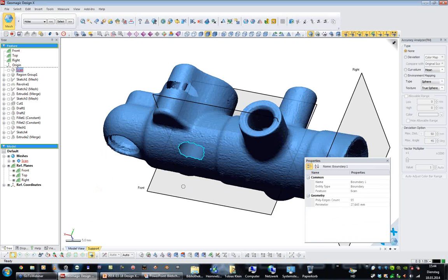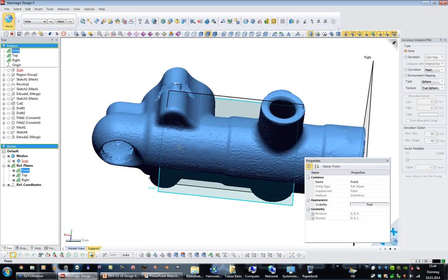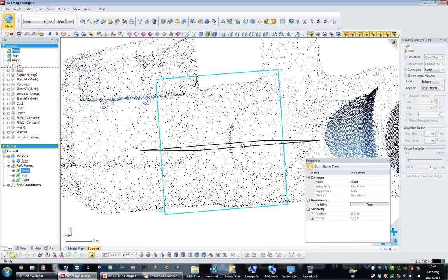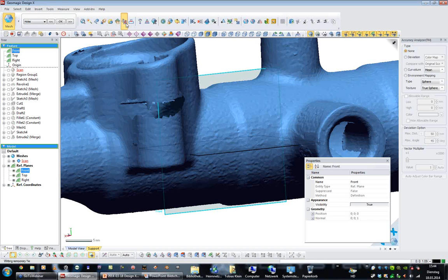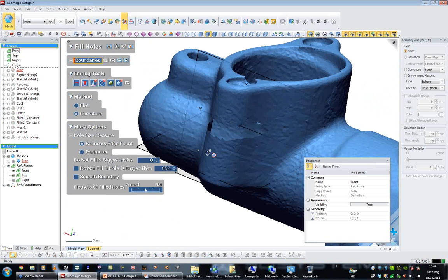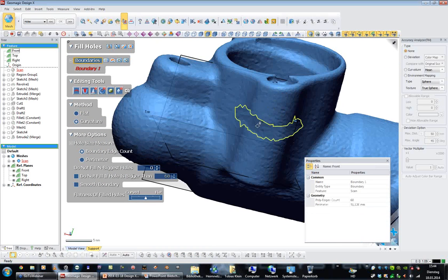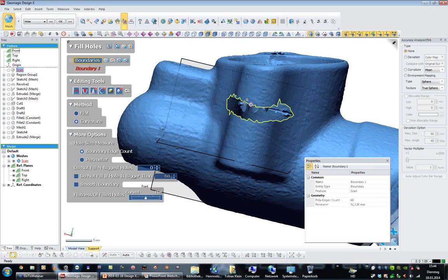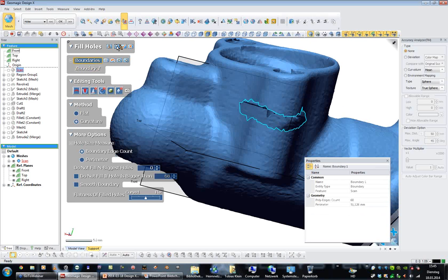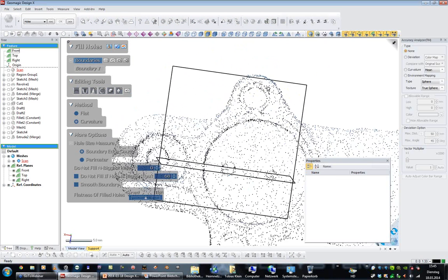This is a single hole filling, and it's just checking the surrounding curvature of the part and filling the hole curvature based and smoothing the boundary of the hole. But it's also possible to use a hole filling tool to fill multiple holes, and this has more sophisticated features like bridging or filling gulfs or removing islands, something like that. So I could just fill that hole in one go, but maybe it works, maybe it's failing. If the hole is like this, then it should work, of course.